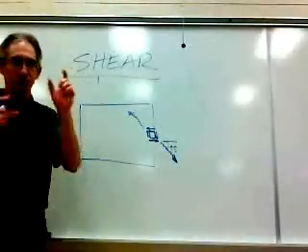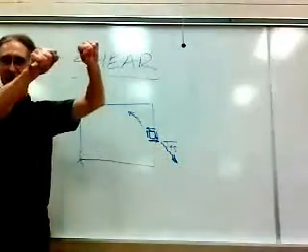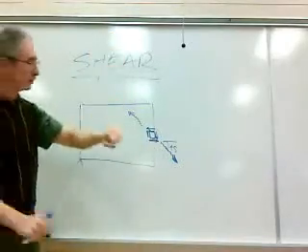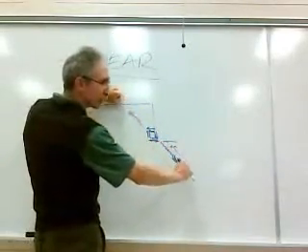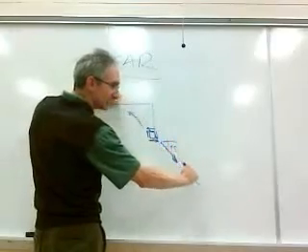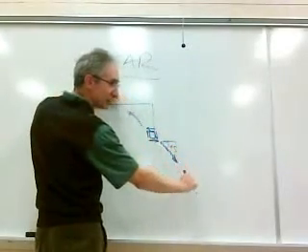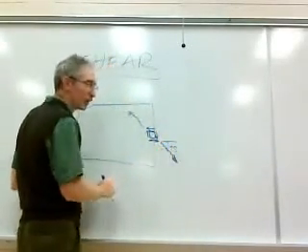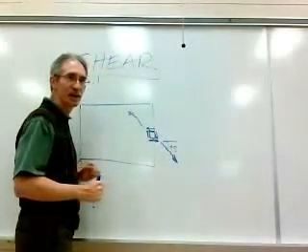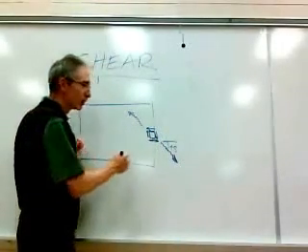Now, imagine this little square of concrete, and I've got these diagonal forces. What are these diagonal forces doing at the corners? How are they acting? Tension. That's a little piece of concrete. Concrete's not real good in tension, is it? Where's it going to crack?